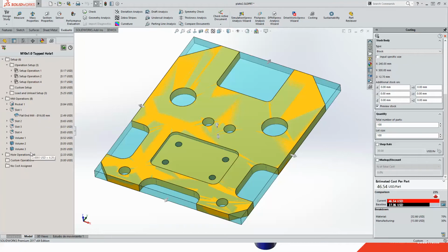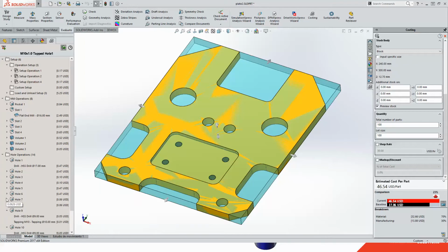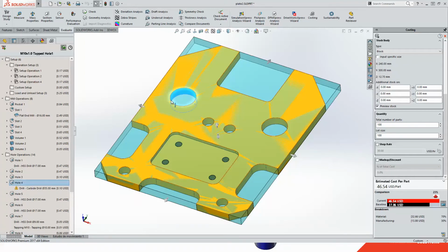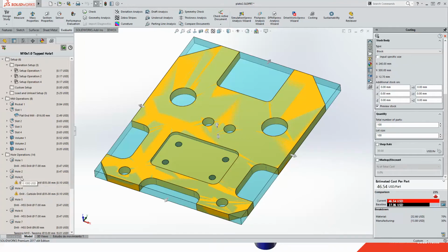Hole operations are something that are automatically detected based on what you see here. Now, the drill sizes that match are going to be the ones that are going to work for us. But when you list any of these out here that maybe are pretty large, like right now we've got this particular size one, you can actually see that there's a warning here that says the drill sizes don't match. There's a couple of holes that actually refers to. Well, these are the type that I might go ahead and take after the fact and proactively switch those over to a mill operation.